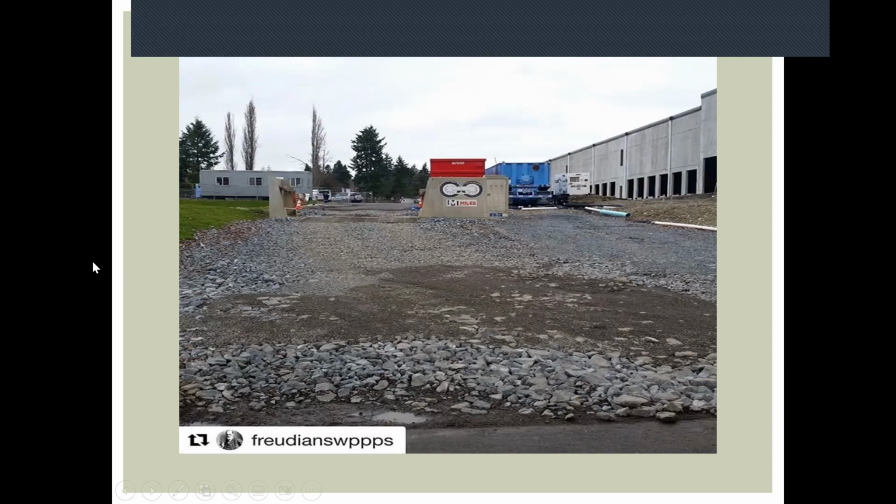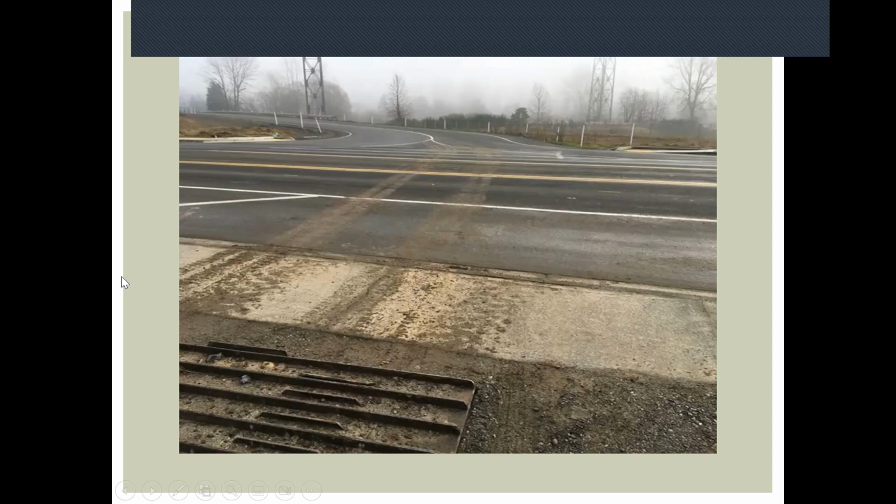These are kind of after the fact, the next couple of slides, but if you're designing plans or reviewing plans before they go out on the street, or if it's something that you can get the contractor to change, putting a tire wash way back in the site and then allowing trucks to drive through dirt after that before they go on asphalt is generally not a good idea. Actually, it's never a good idea. So the placement of something good turns out to be a bad thing.